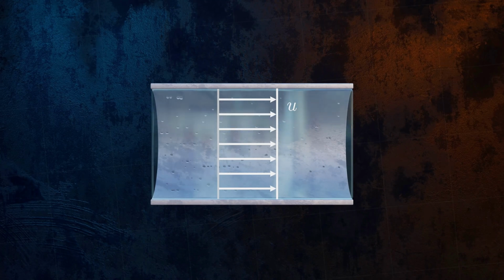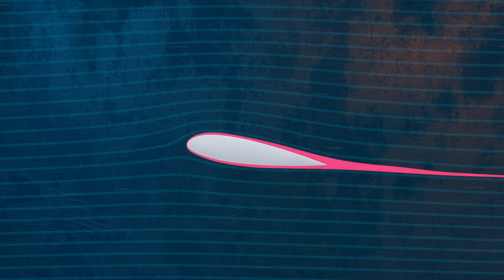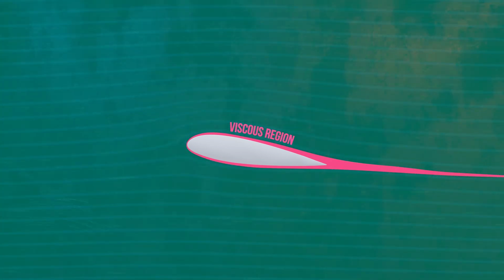The existence of viscosity can make modeling flow quite complicated, and so engineers often try to neglect viscous forces where possible. The assumption that viscous forces are negligible is typically only applied to certain regions within a larger flow system. It's never valid for flow close to a boundary, for example, where viscous forces are always significant. But outside of the boundary layer, at high Reynolds numbers, viscous forces can often be neglected.